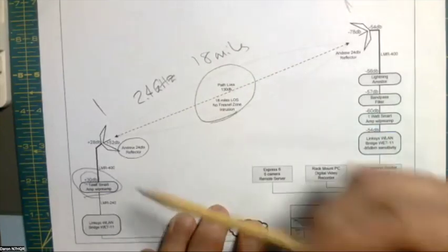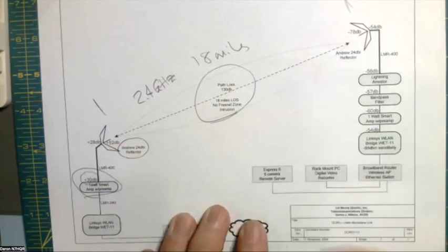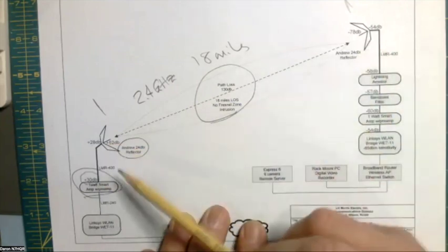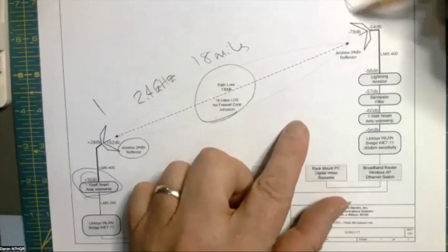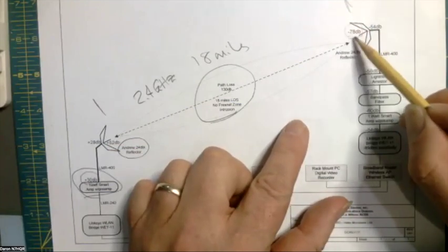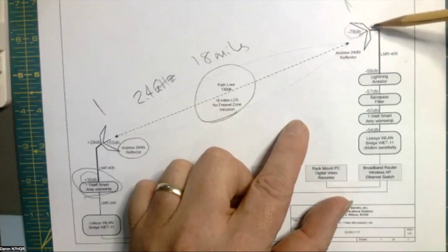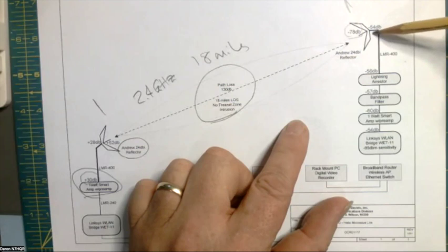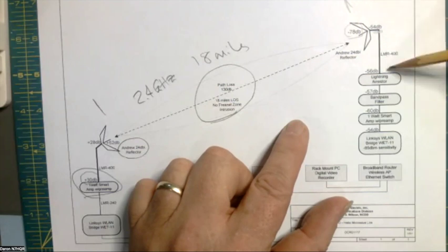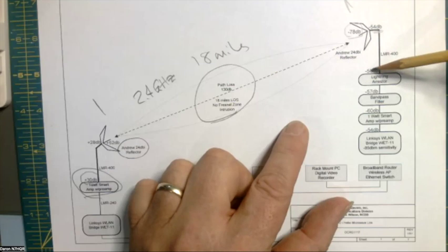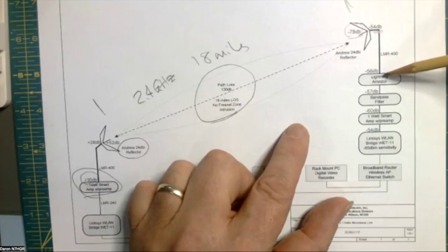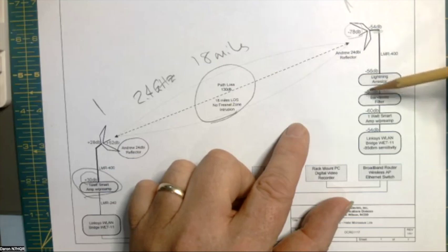So these calculations, the feed line loss is dependent on the frequency, as is the path loss. So by the time we get up to the top of Mount Hebo, our signal strength is negative 78 dBm roughly. And then we have the same antenna, so we gain 24 dB. So now we're down to negative 54. We have another piece of feed line where we lose a couple more, so now we're down to negative 56. A lightning arrestor that loses 1 dB when you put it in the circuit, so we're down to 57.